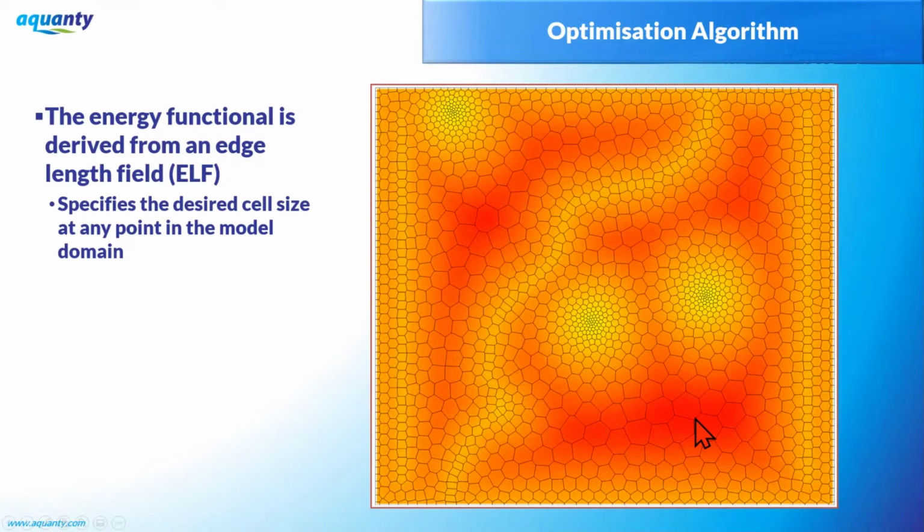But it can be controlled by the user both globally, through parameters influencing the local feature size calculations, as well as locally, for example, by adding polygonal regions in which maximum cell sizes are specified, or resampling along polyline features such as streamlines with points at different spacing intervals.